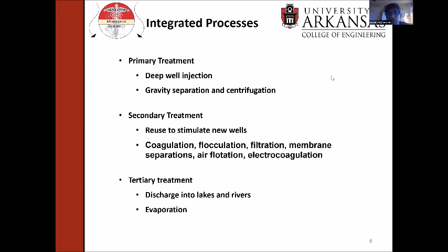And the problem is that this water contains fracking fluids and other things that cause corrosion of equipment. So typically things like coagulation, flocculation, filtration, electrocoagulation are used to treat the water somewhat more. And then tertiary treatment refers to basically evaporation, distillation type processes, if you want to actually treat the water and discharge into lakes and rivers.